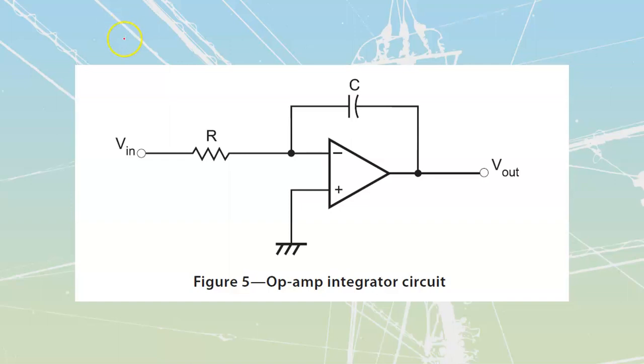There's this thing inside of controls called PID: proportional, integral, and differential. That is basically like saying, the history of where something is, what we still need to expect for it, and what we currently are doing are three ways that we look at how we adjust the speed on something like a motor. Proportional, integral, and derivative, we combine all three of those: where we currently are, where we were before, and how far we have left to go is the short form for these. Then we can figure out exactly how fast we should be running a motor, etc.